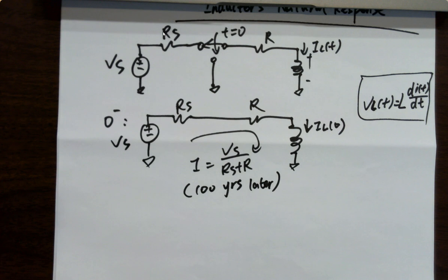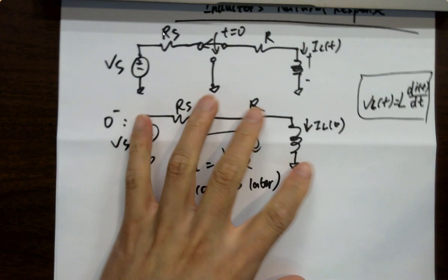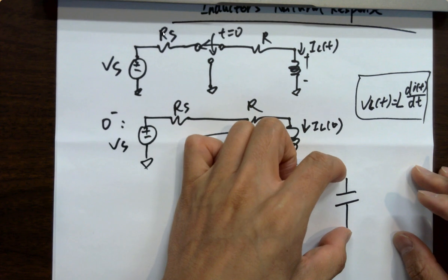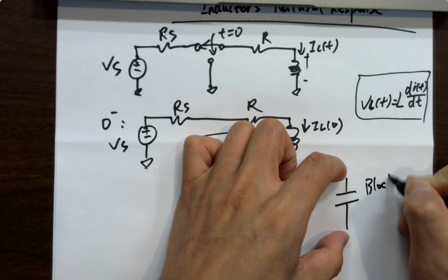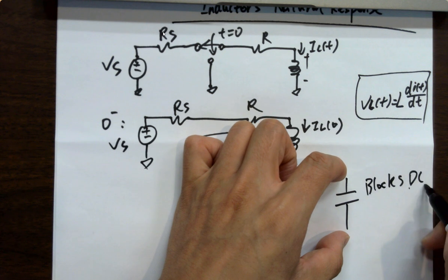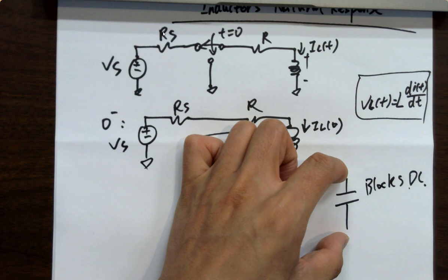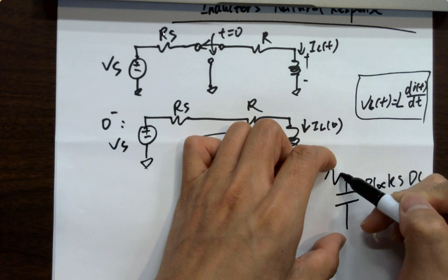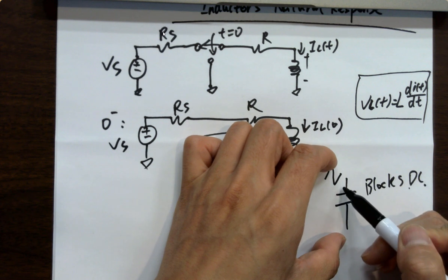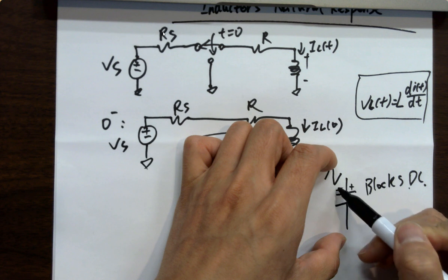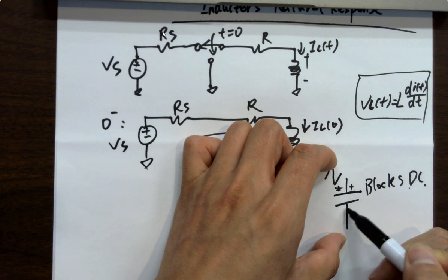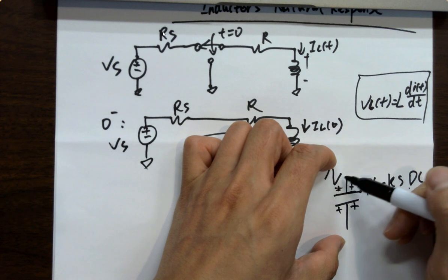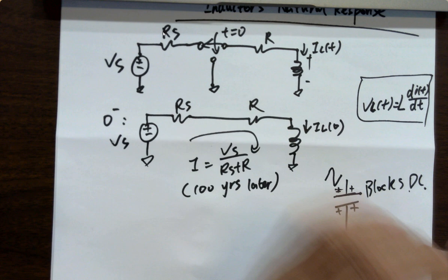One thing you need to know: capacitors will block what and pass what? Block DC, right? Direct current, which is a static voltage, will be blocked because of the disconnected circuit. If you run an AC voltage across it, it's pushing charges back and forth. On one plate, it's going to repel charges on the other plate as well. So it seems like it's passing the AC voltage physically, but actually it's not.